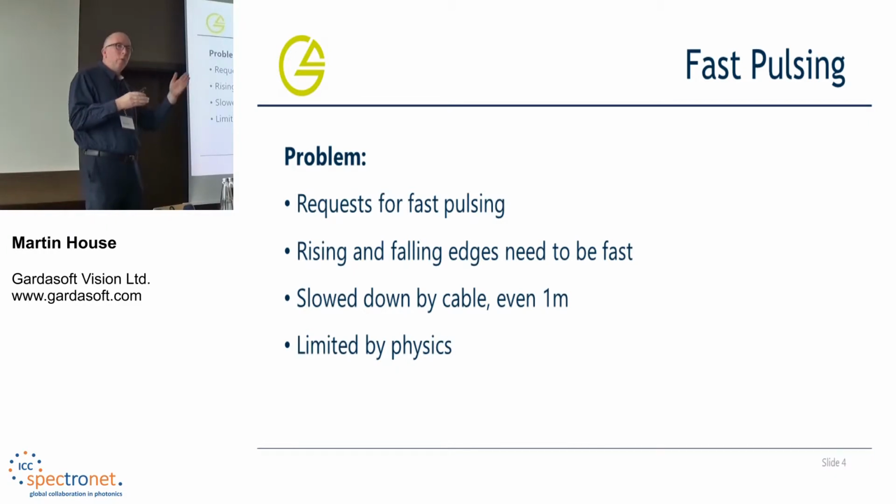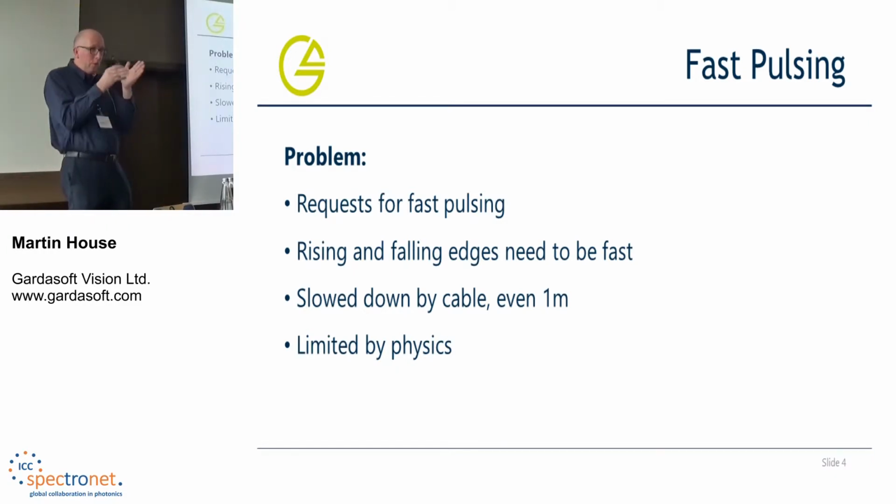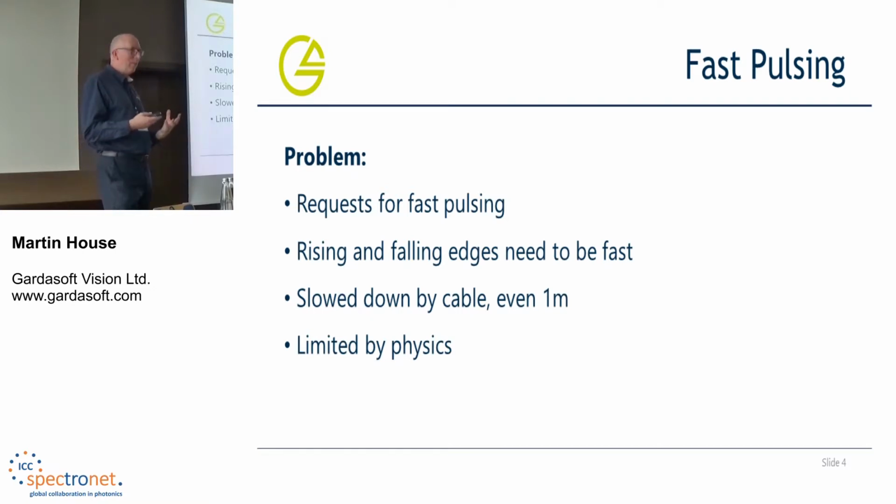The further away, the worse it gets, and the optimum is right next to the light. And the other issue is how much current you need to drive to the light. Unfortunately, the way line scan is going now, it's going faster and faster. Because of that, the shutter speeds or exposure times are much shorter. Therefore, you need to get much more illumination into the camera. And all these things are fighting against getting a fast rise time.